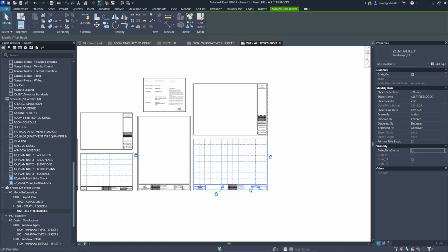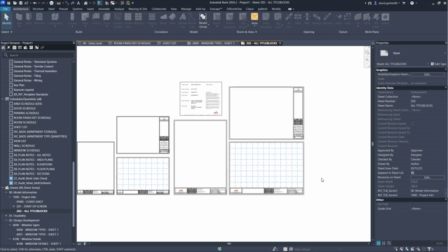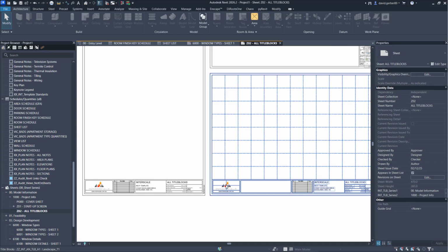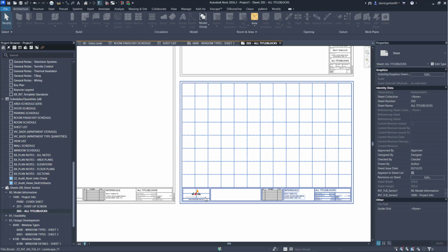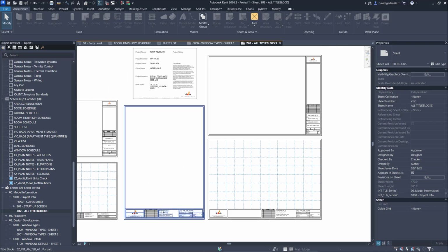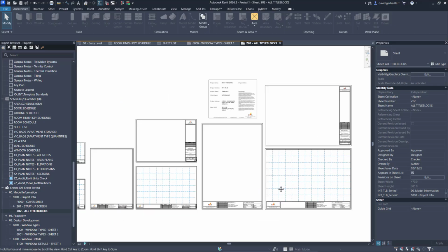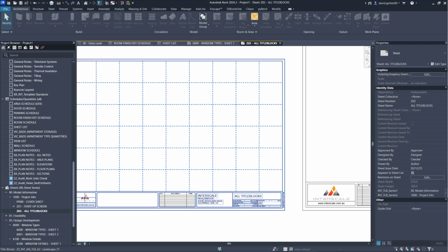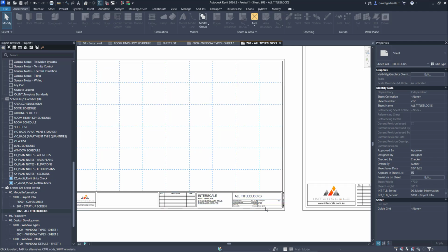And you'll notice all the different types of title blocks visibility here. If you want your logos and your revision schedules, they automatically update in a formula. So just be mindful when you put in a new logo for your sizing. And all of that information that I spoke about earlier, your project information also populates into here, not just that starting view.